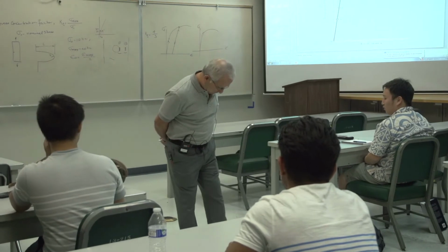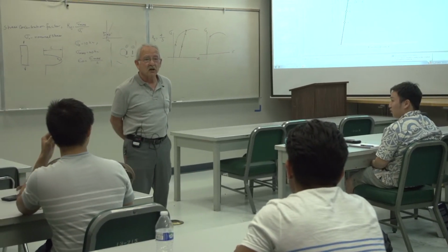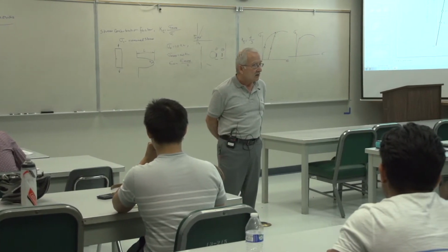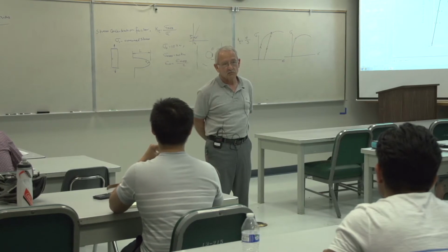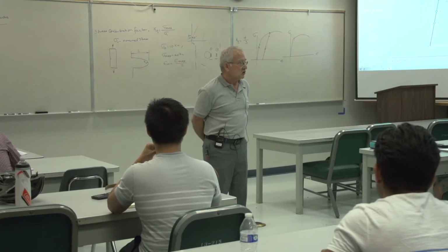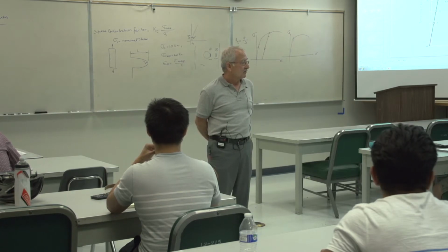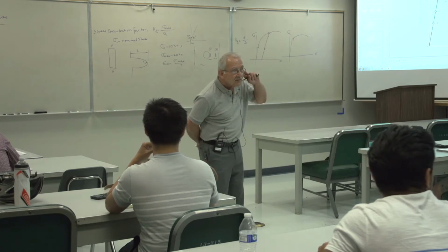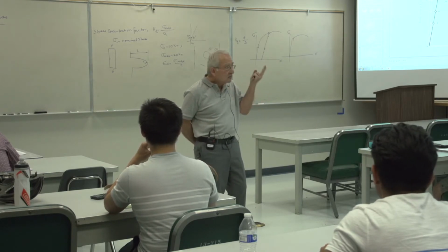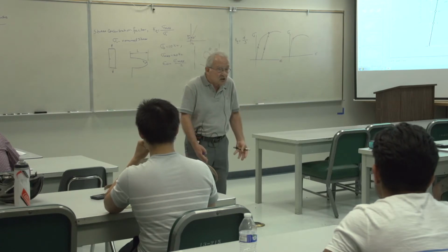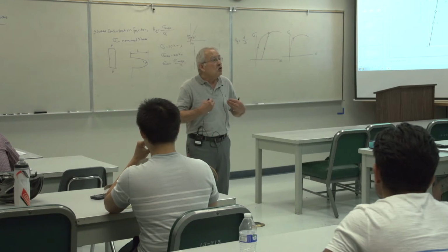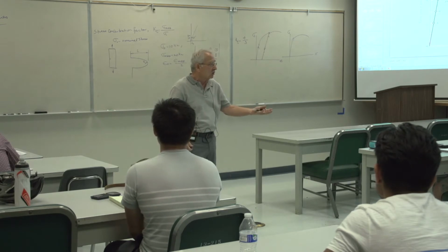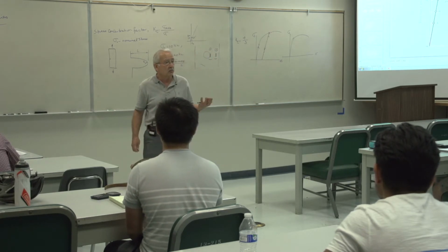Let's say the cross-sectional area of my 2 feet combined is 15 square inches, okay? And I weigh 150 pounds. What's the average stress? 10 pounds per square inch, right? So in order to create a stress, you need a load. You need an area on which the load acts. Now, this could be normal stress, it could be shear stress, but you need a load and you need an area.